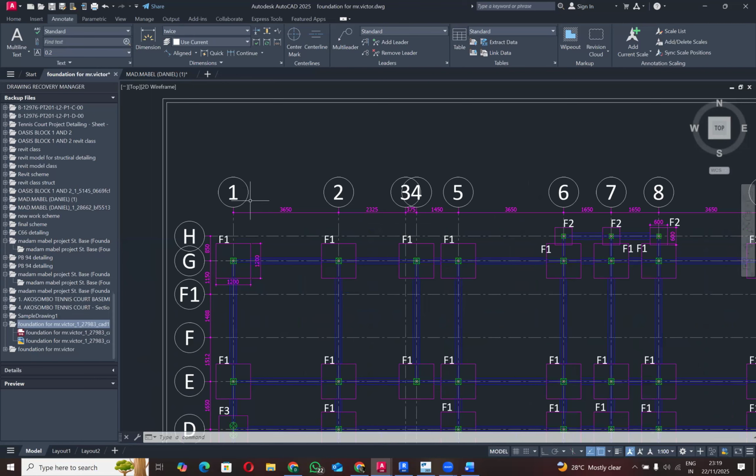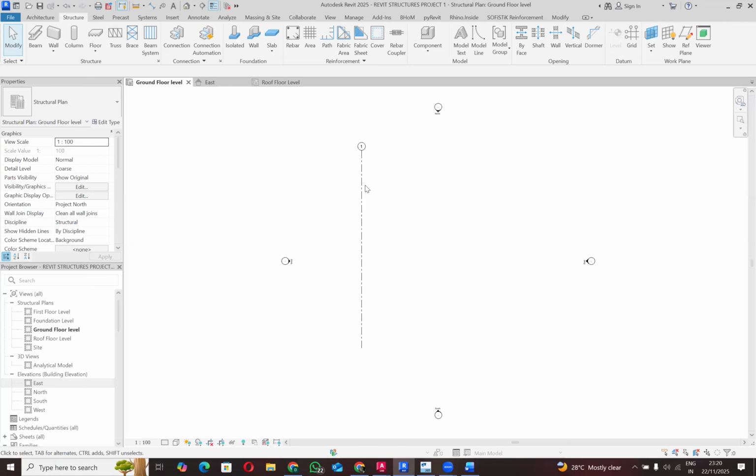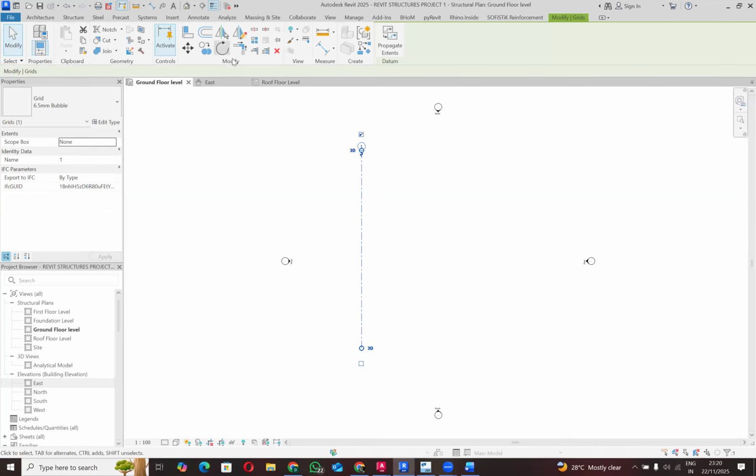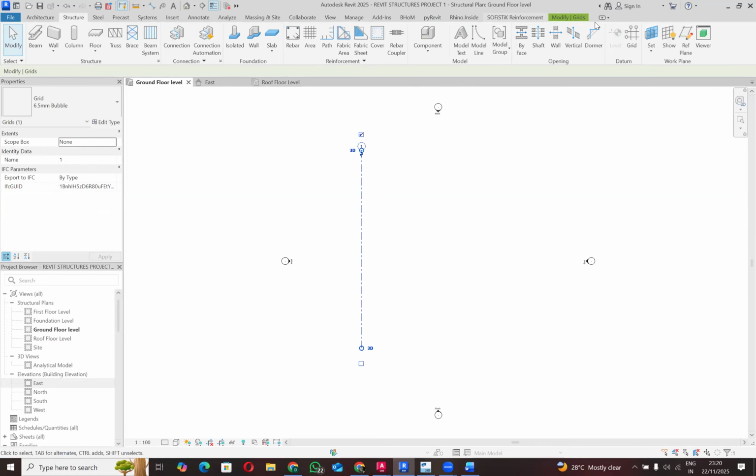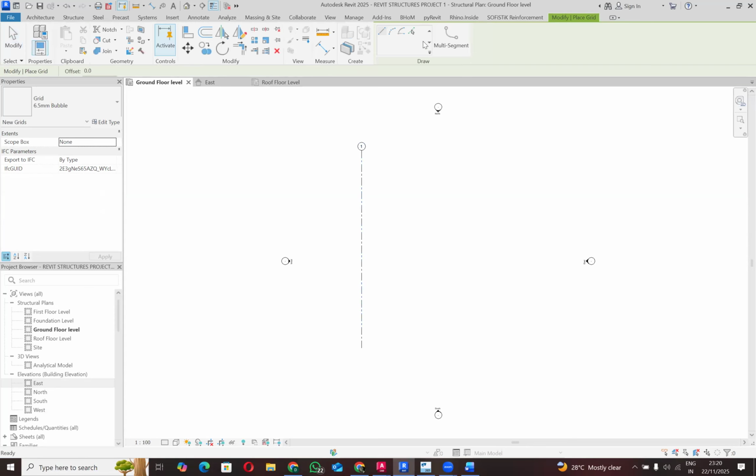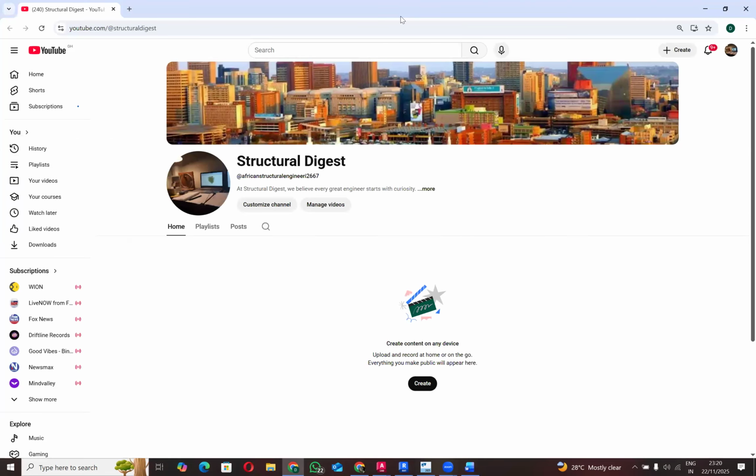So let's do it. Our next grid line is 3. It has a distance of 3650. So you have to replicate the same thing. You go to structure, click on grid, click on the context panel, pick line with the arrow, you select that one. Then you're doing this.